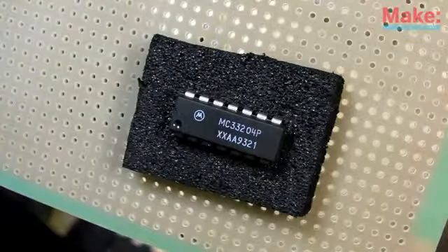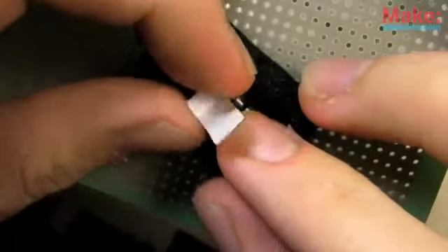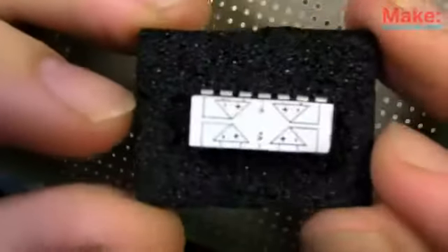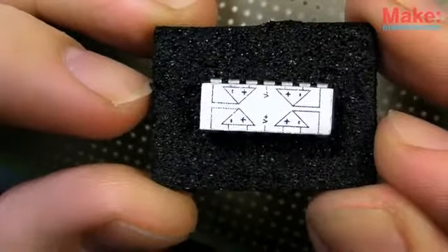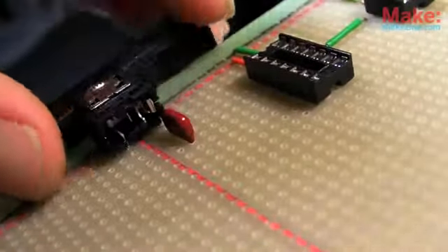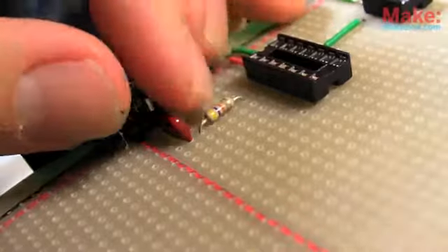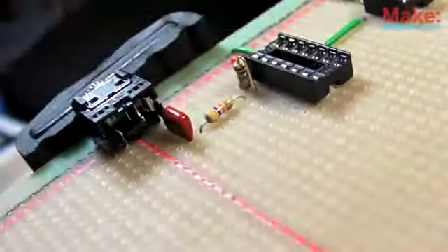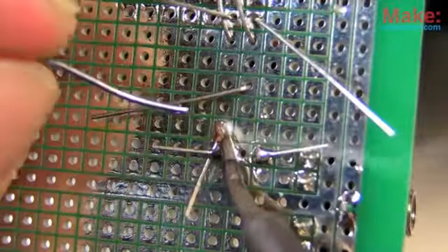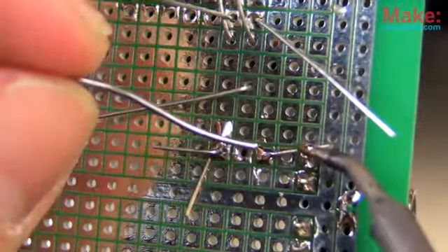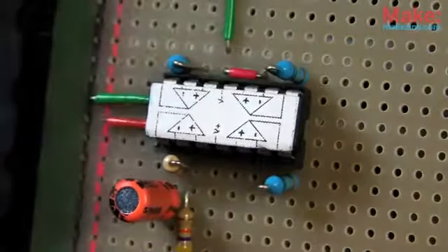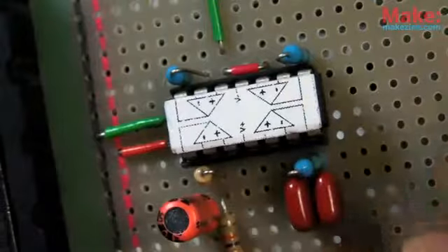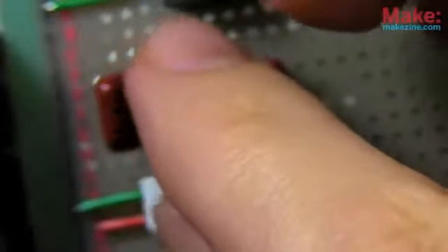Having multiple op-amps on a single IC can get a little confusing, so I printed out a small label to keep track of each pin's connection. The fact that our 3 bandpass filters are so similar means we can arrange each of them in nearly the same way, which is a welcome time saver.